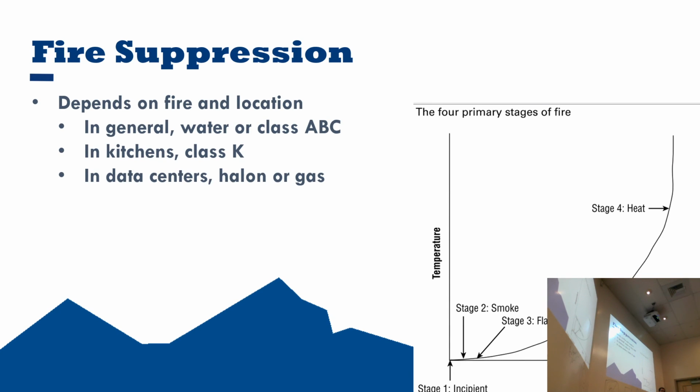Let's talk about fire suppression. All right. So this is going to be highly dependent upon where you're wanting to be. The answer is not just let's plop a sprinkler system in every building. Okay, could be an answer, could not be. So in general, you have a standard office fire, put it out fairly easily with either water, like sprinkler systems like we have in here, nice little concealed units too, or a Class ABC fire extinguisher. That'll put out most fires, right?